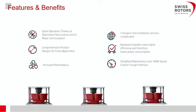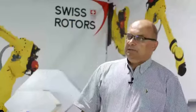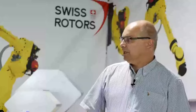What are some benefits and features? If the impeller is smaller, then all sizes of the air handling units are smaller. The flow through the air handling units is much more equal, and there is no peak with very high speed and then an area with very low speed or almost no speed inside the air handling unit. And then we can save cost, because, as I mentioned in the beginning, smaller EC motors are much cheaper than bigger EC motors.